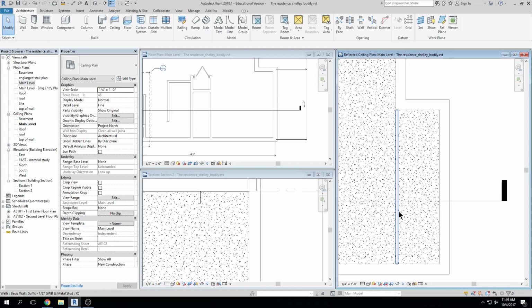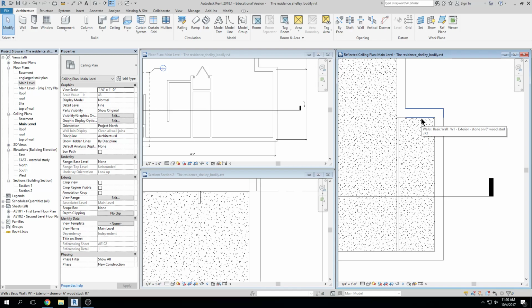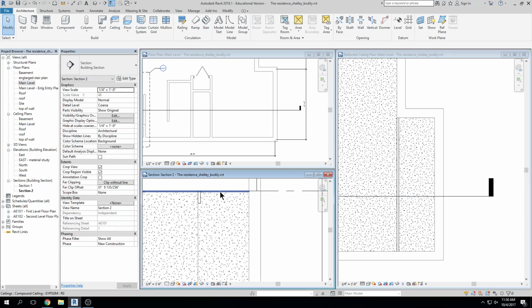Okay, so there's my defining wall, the framing. We're not going to really show framing here necessarily, but what we are going to do is have a ceiling type that has a stud and gypsum board associated with it, right, because it's dropping down. First of all, I already have some ceiling coming in here, which is at the wrong level, right? The ceiling is up there.